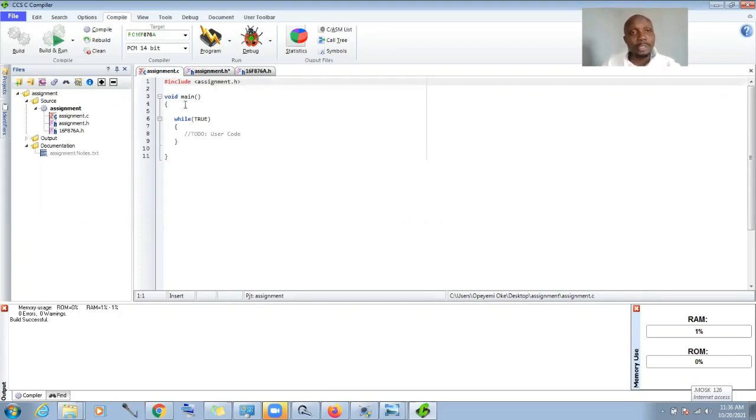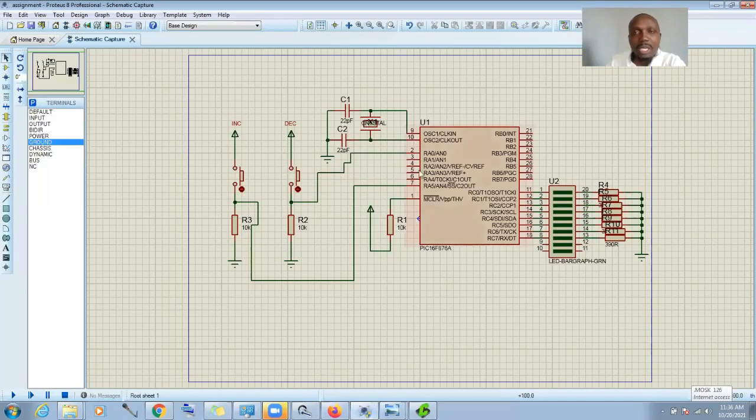So what do I do here? Like every project, I also forgot to do that. Let me go back to the circuit diagram. For every design, it's very important that you have one pin that is your power pin. That is there to signify that your project is working, that your code actually started well, as against having an LED attached to your power supply. It's good that you have that on any of the pins on your microcontroller. We've already established that in the several classes we've had.